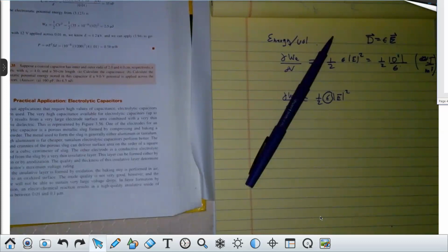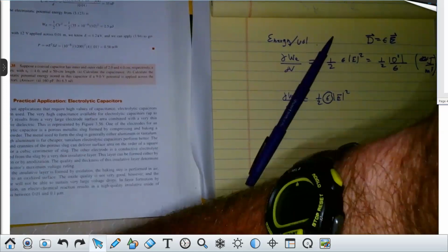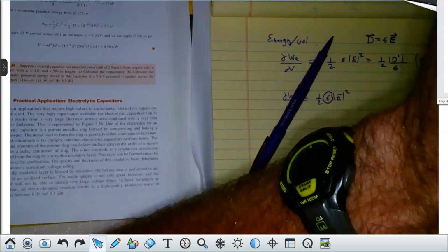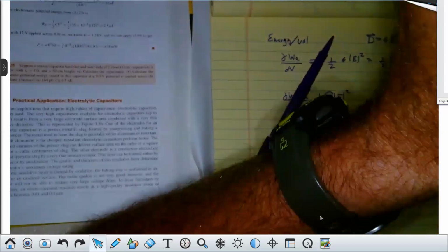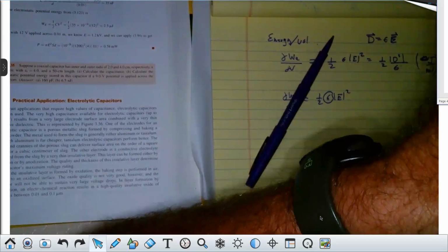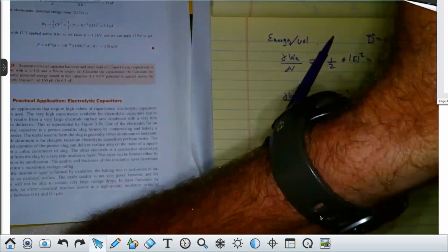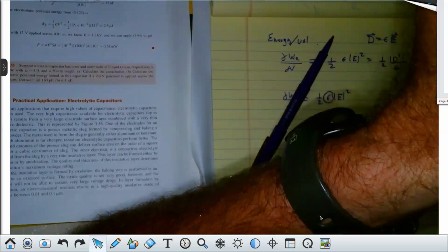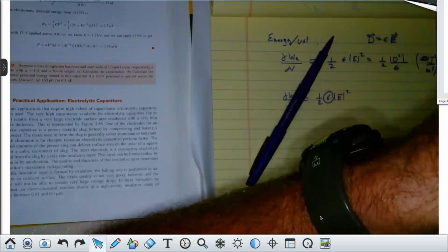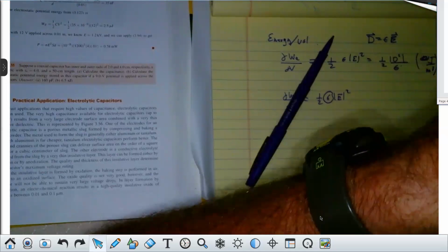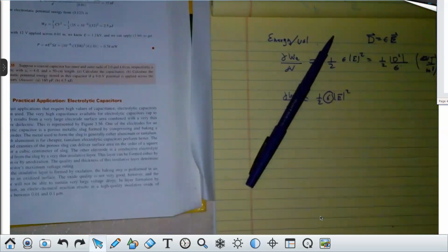Well, what's really going on is that whenever you see an electrical spark, you see ionization of the atmosphere, and the light being emitted is basically the electrons falling back into their rest state, and they're emitting a photon of light. They're being ripped away from their rest states, and then they relax back into it, and that's where the photon comes from. So in order to do that in just standard conditions in the atmosphere where you and I are living right now, it takes about 3 million volts per meter. Well, 3 times 10 to the 6 volts per meter on 2 parallel plates would do it.